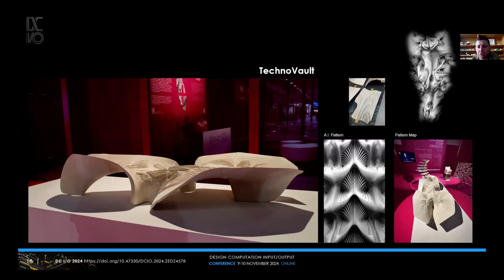So Technovault really aimed to showcase the integration of additive manufacturing, again, in ashlar construction, deploying a relatively new concept, additive stereotomy, a departure from the traditional stereotomy of vaulted or shell construction, historically cut from discrete solid ashlars. Instead, this concept considers constructing from discrete ashlars through 3D printed blocks. This gives us the ability to embed joinery and any kind of connection details. It's also very advantageous to reduce overall costs because we're not relying on specialized labor to sculpt and edit the material.